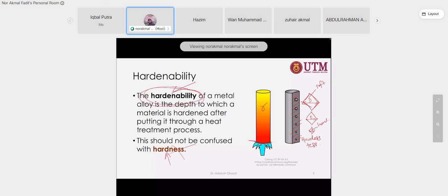Of course, plastic deformation occurs, which is the reason you can see the shape of the indentation. When it indents deeply, the size of the indentation becomes the indicator of how soft or how hard the surface is. So if you see this kind of varied size, this one is hard, this one is soft.